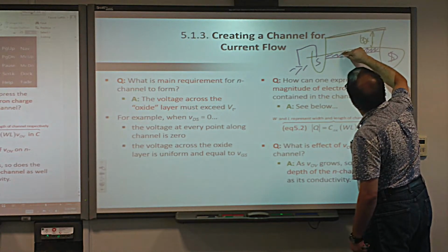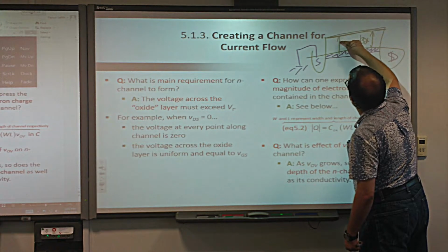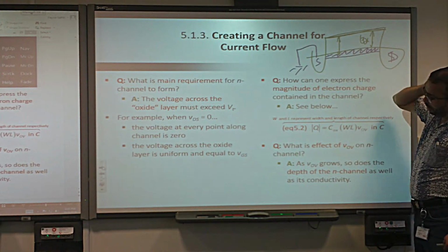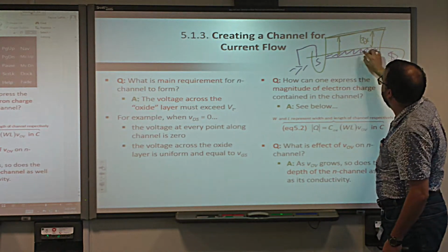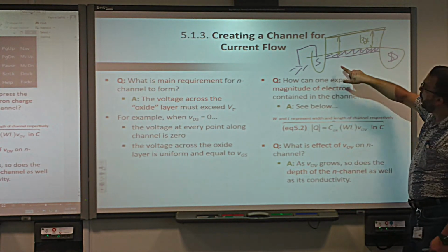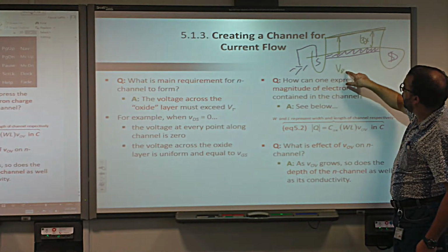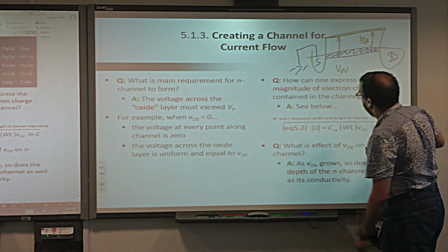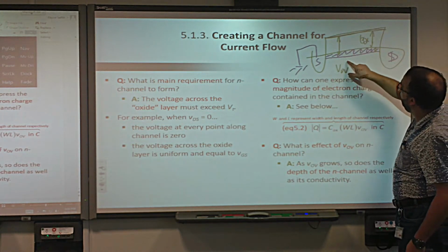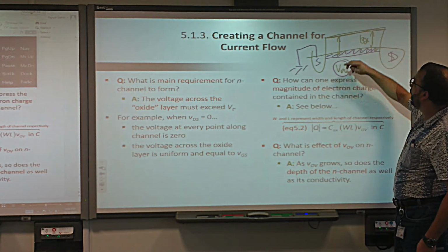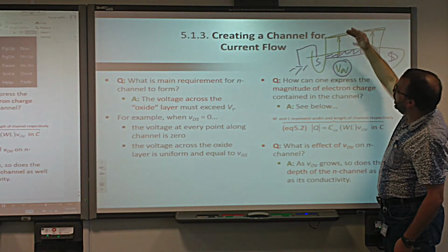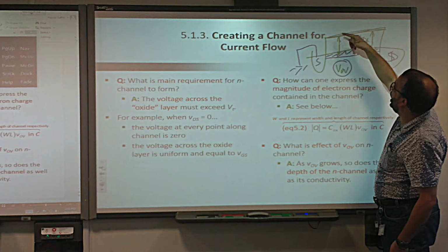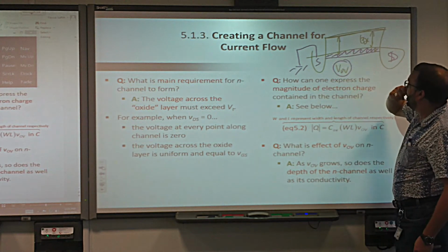What else? We know the voltage between the gate and the channel. Basically the charge in the channel will feel the overdrive. It means every single part of this channel, every single charge here, will feel the overdrive voltage, that is the voltage of Vg minus Vt, the part above Vt. Below that there is no channel. Above, we have that voltage that each charge here will feel.